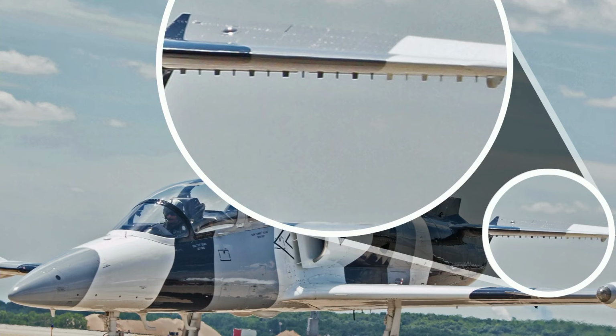And so those vortex generators are essentially going to keep the airflow energized and attached to the bottom of the horizontal stabilizer. And so if the horizontal stabilizer starts to get close to supersonic flow, the VGs will both delay the shockwave, they delay the critical Mach number on the horizontal stabilizer, and if a small shockwave forms, they can help pump air into the boundary layer to keep it attached or minimize the amount of separation.